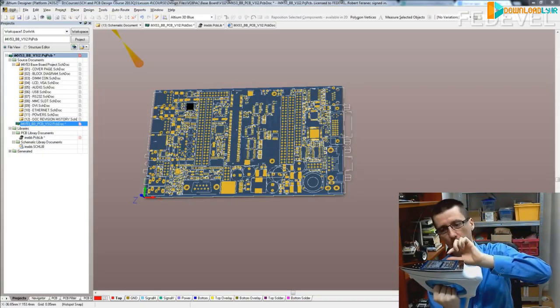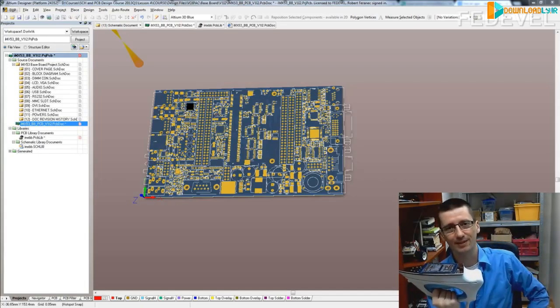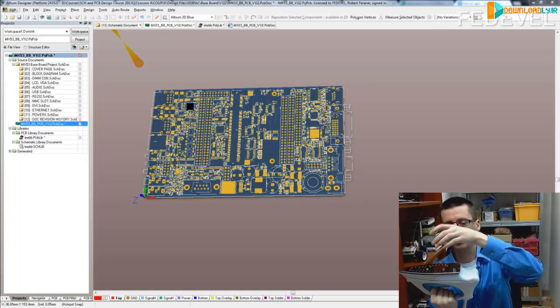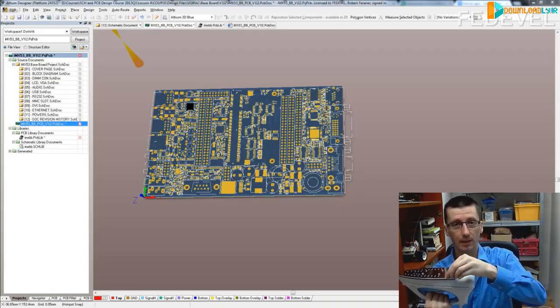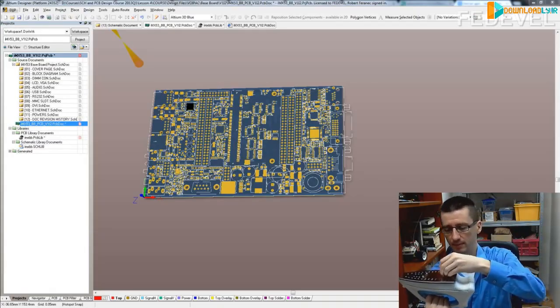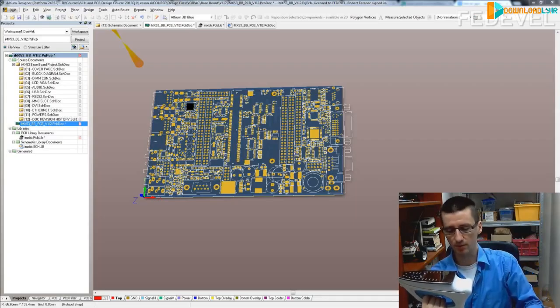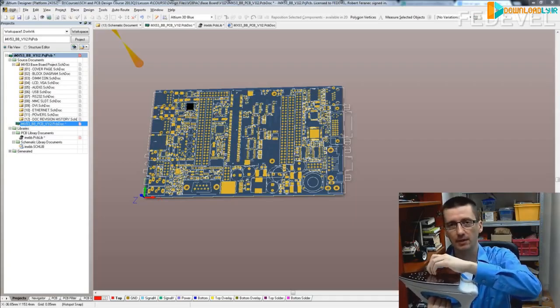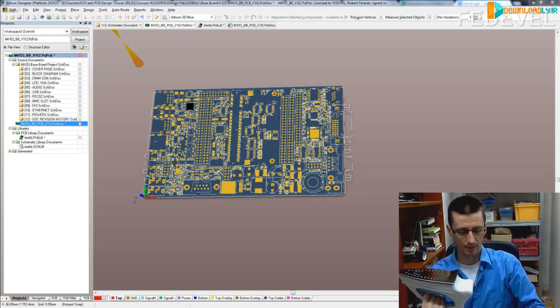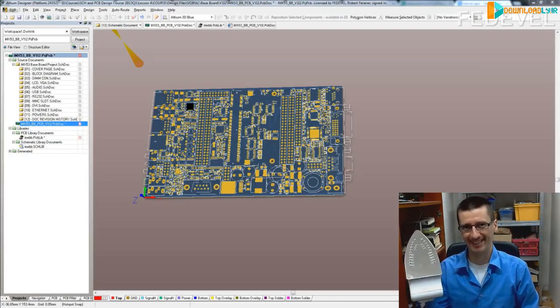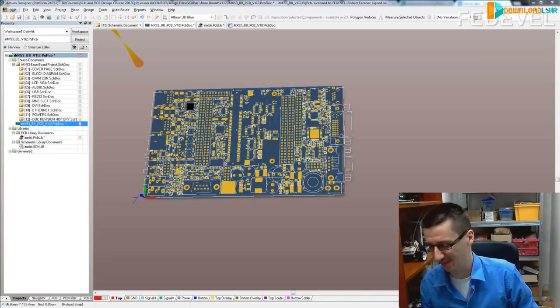So there was a small gap, and we were soldering the BGAs this way. I don't know if it's still possible with lead-free parts, because the temperature for lead-free is higher than for leaded. But what I know, we didn't use the steam. That I'm pretty sure about.